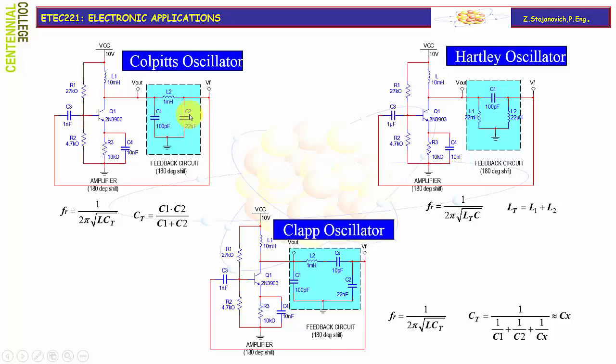In most cases, this is the situation which we are facing in our lab experiments, where parasitic capacitances are actually capacitance between breadboard rows, which has a certain capacitance associated with the mechanical design of the breadboard rows. Adding this small capacitor Cx, now we will have three capacitors in series, thus making total equivalent capacitance equal 1 over the sum of reciprocal values of C1, C2, and Cx.